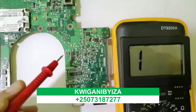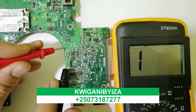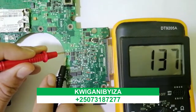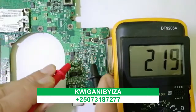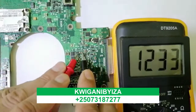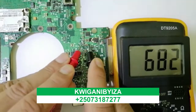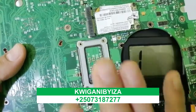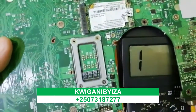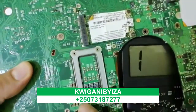But for the ceramic capacitors that do not belong to the CPU circuit or other chipset circuits, you will find a normal reading, as you can see here, for example. Do you see? Normal reading. Okay, any ceramic capacitor here, if I find, for example, a low reading, it means we have a short circuit. But here, guys, I want to add an exception. Basically, this is a shorted motherboard. The short is in the CPU circuit, okay?